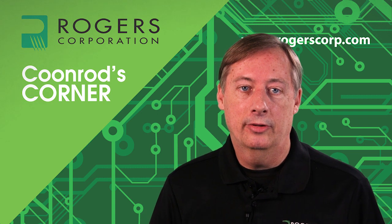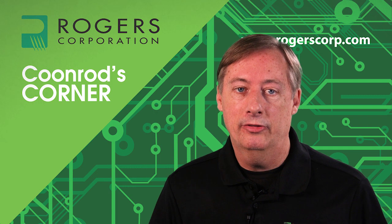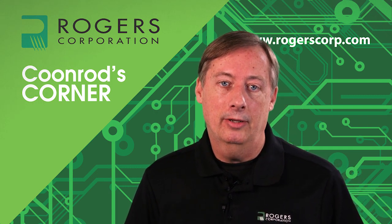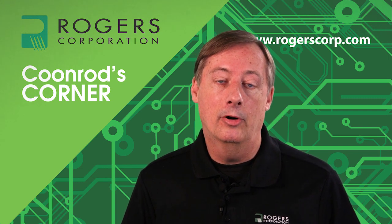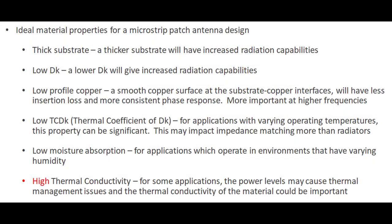For antenna applications, there are several material properties that are critical, and there are also several things to think about for circuit fabrication that can influence the antenna as well. So with the next few graphics, I'm going to talk about the material properties that are critical and why, and then also we'll talk a little bit about circuit fabrication and how that can impact the performance of antennas at microwave and especially at millimeter wave frequencies. The information shown here is related to material properties, and there are several different properties to think about. First off, most of these properties are geared toward causing radiation for the antenna patch itself.